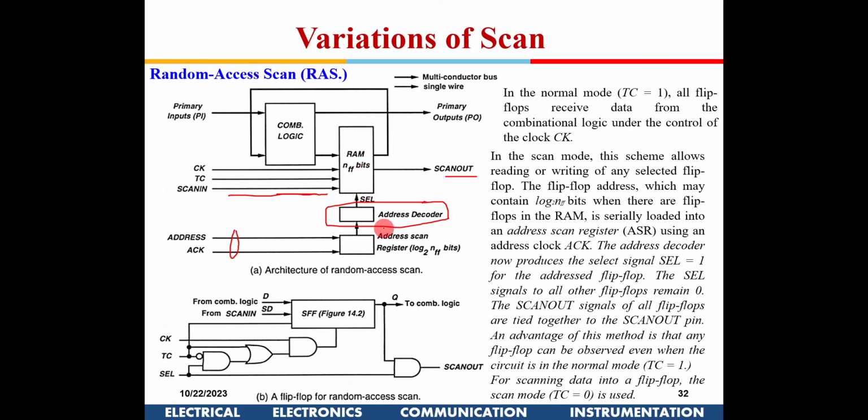So in the entire flip-flop chain, instead of pure serial scanning, in parallel we can push in our required data to one of the RAM cells. So that helps in certain cases. This is not generally done, but this is an option which is available, in certain cases where the testing requirements of each combinational logic are varied.